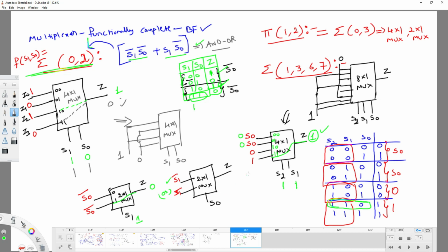So like this you can use multiplexers to construct circuits. Right? In the coming class, we'll see a few more examples. Now, can the same circuit be constructed with the help of 2 by 1 multiplexers? Yes or no? Yes, right. As we can construct it with 8 by 1, I can construct it with 4 by 1, and I can construct it with 2 by 1, right?